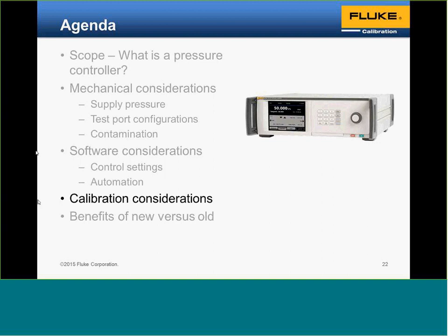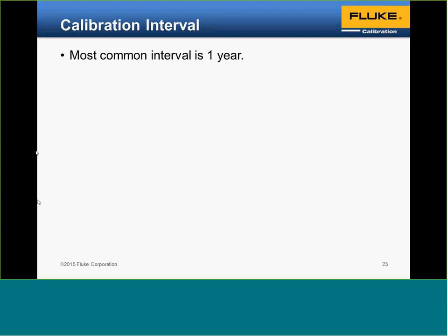Some considerations when it comes to the calibration of these devices. First is the interval, which is one year. The pressure controller with an onboard sensor will need to be calibrated as well. The common calibration interval for that is a one year interval, depending upon your application.